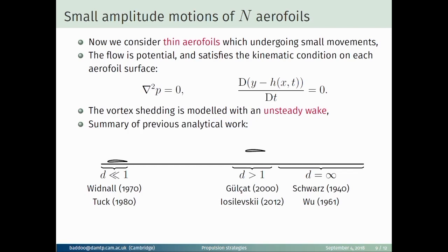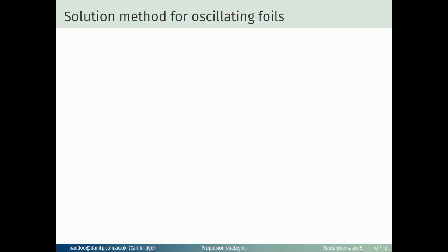And as far as previous work is concerned, there's been quite a lot done into the extreme ground effect problem, that is d much less than 1, and a bit of work done into the weak ground effect problem, that's d greater than 1. But as you can see, there's quite a large gap here where for d between 0 and 1, not much has been considered because the equation is very difficult to solve there. And consequently, the present analysis will be valid for all scales of d, so all along this diagram.